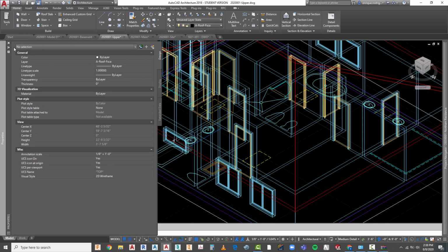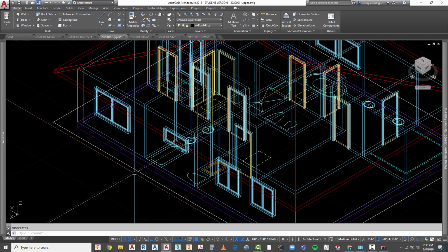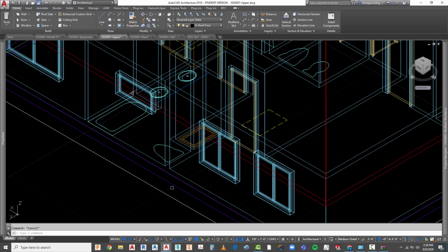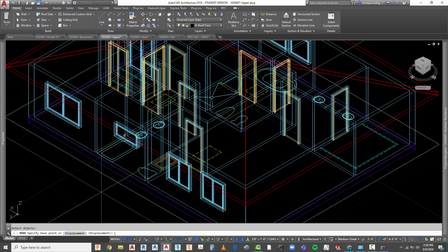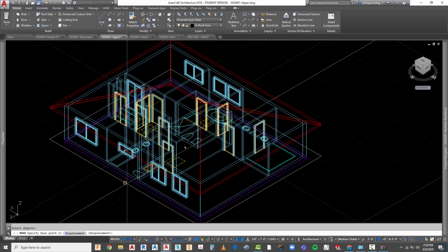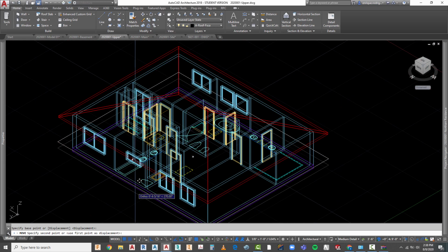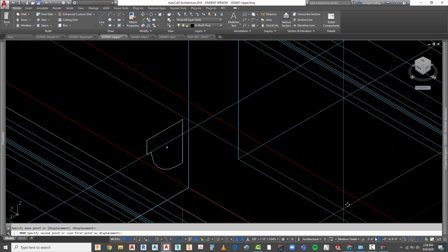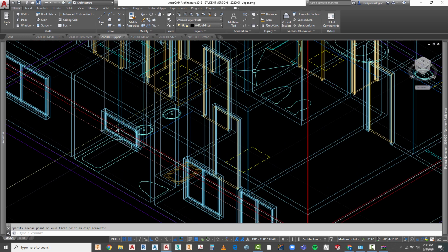Let's go ahead and get this minimized. Select my path, enter. I'm going to try to find the midpoint or the end, which should be one and the same in this case. I'm going to move it straight up, and I'm going to line it up with the top right in here. Now once again, it's not letting me, so I'm going to turn off my Z again and bring this up to this point right there. Let's give this another shot.